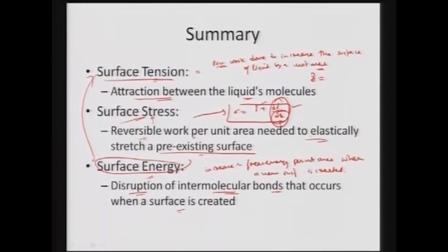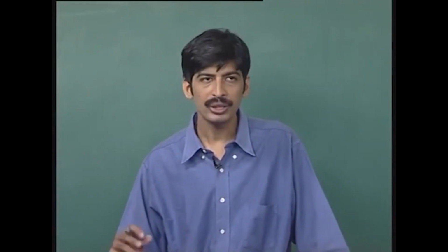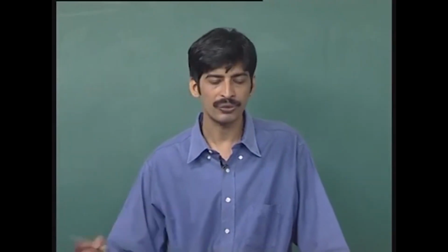We can also evolve the surface stresses via splitting and then stretching, or first stretching and then splitting. Once we are splitting, we are creating two surfaces and then we are stretching them. That means we are letting surface stresses act on it, because once we split, we have two additional surfaces generated. Whereas in stretching and splitting, we take only the deformed surface and then split it. So we can allow surfaces to do additional work in reaching the final state.